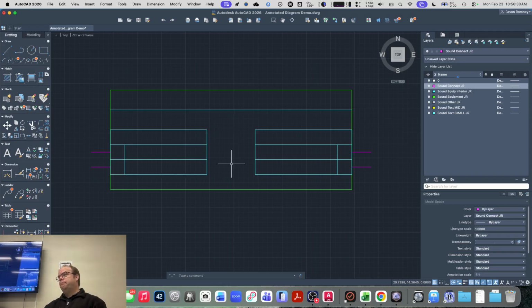Yeah? So that's why I want to leave those little overlapping lines. And the way, yes? It won't snap to the midpoint, it just snaps to the two. You may not have midpoint snap turned on. So right-click on your object snap and turn on midpoint snap. There you go.